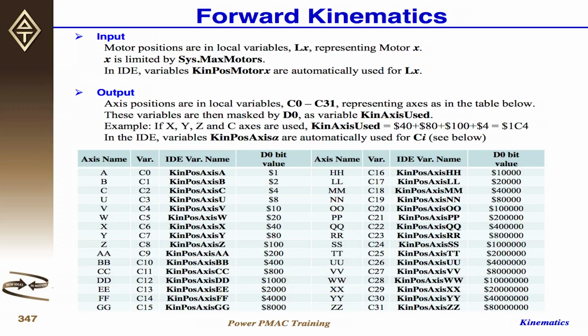Which means I have to prepare all those buffers to say, okay, motor 1 setup is what? Motor 2 setup is what? So I have to prepare that. So you have to set this to a minimum value for your system to reserve all those buffers, which you may not use, because like motor 255, you're not using. But if you didn't set this number low enough, then we actually prepare that for you. Then that's not used, so that's wasted. That's why we have this system max motors number for your definition.